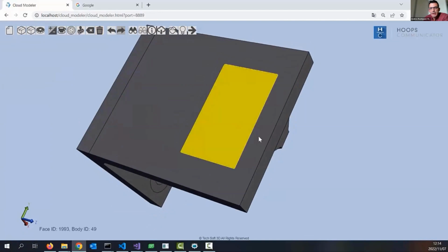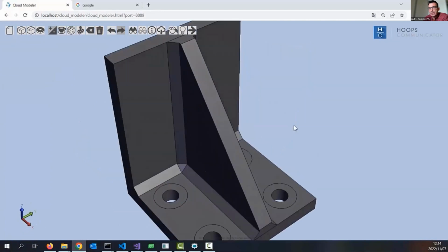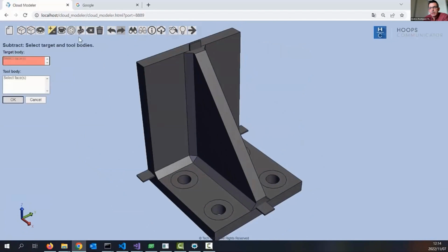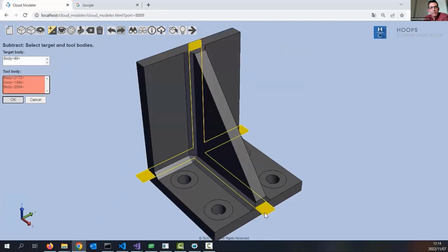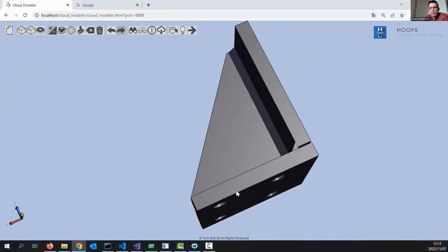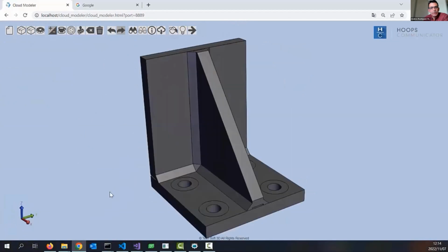The three plates in this product are not actually attached to each other, but are connected by fillet weld, as you saw. And we'll be modeling this by introducing a small gap in between the plates using temporary thin sheets and subtracting them from the geometry. Okay, so with these edits, we now have a geometric model of the manufactured part. We can move to the FEA space.